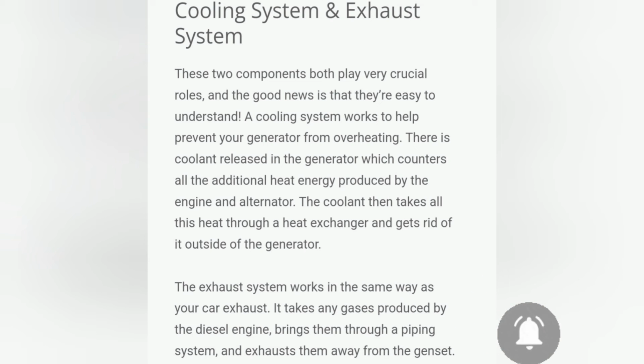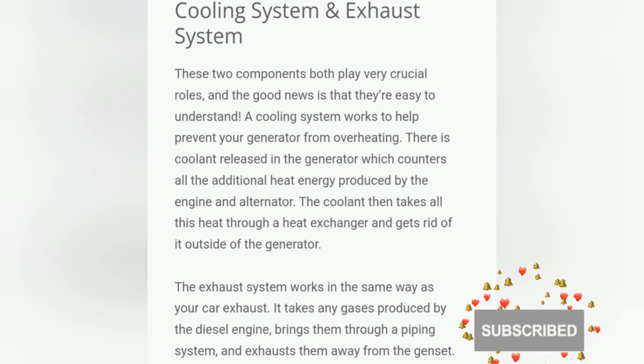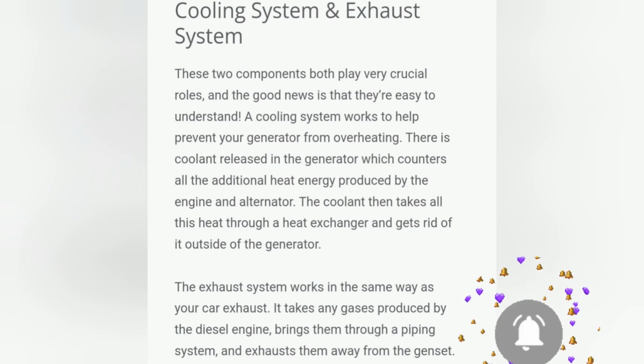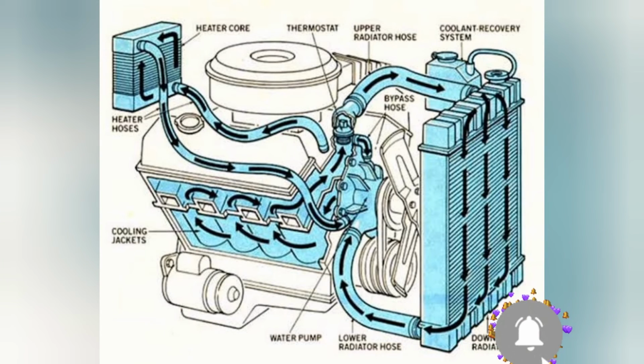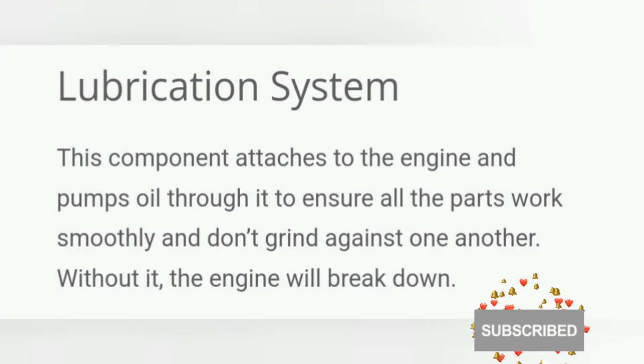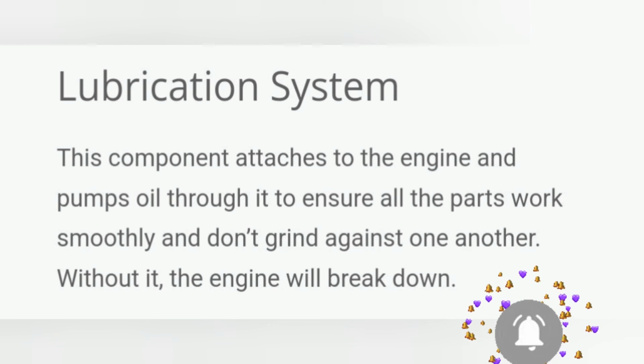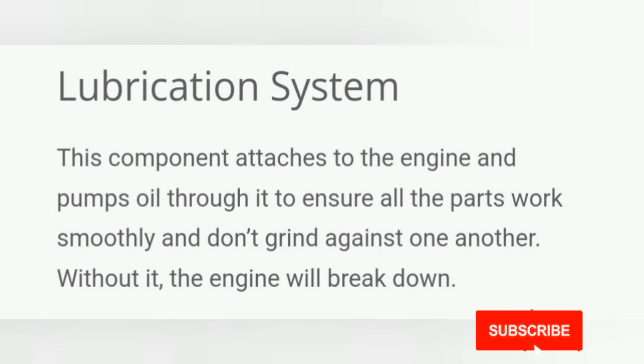Why? Because the cooling system and exhaust system are the main things. If the generator runs continuously, it will create a lot of heat for the total equipment. So for that heat we need to cool it, and we use coolants as well as the water system. A radiator will be there. Using the water and this liquid coolant, we will reduce the heat of the engine. For that only, the engine lifespan will also increase.